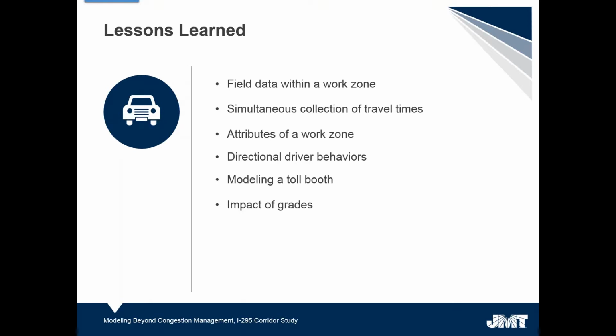Also learned about the attributes of a work zone, like how work zones impacted drivers. And then also for driver behaviors, we saw that this study area was very directional in regards to driver behaviors. So if a driver was coming from the New Jersey side and entering Delaware, and vice versa, if there was a driver coming from Delaware and entering New Jersey, they each drove very differently. So we actually implemented different driver behaviors for each side.